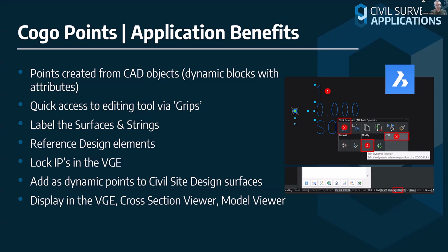Now, you can also, and this is just as a basic way of using them, assign them as just regular CAD points to your surface. So as you'll see in a second, when I look at the point style, we'll be able to adopt a CAD point onto that point style, and you can add that into Surface Manager as a dynamic point rather than having to linearly create objects to give you elevations.